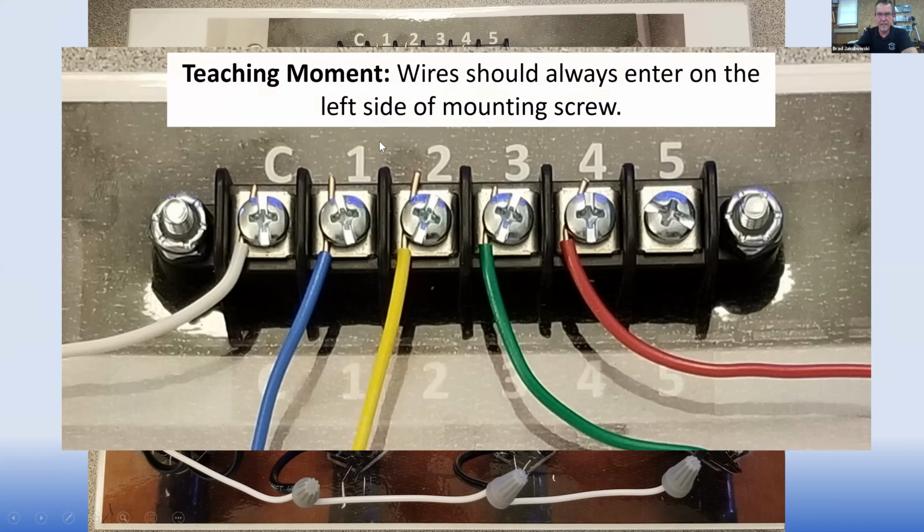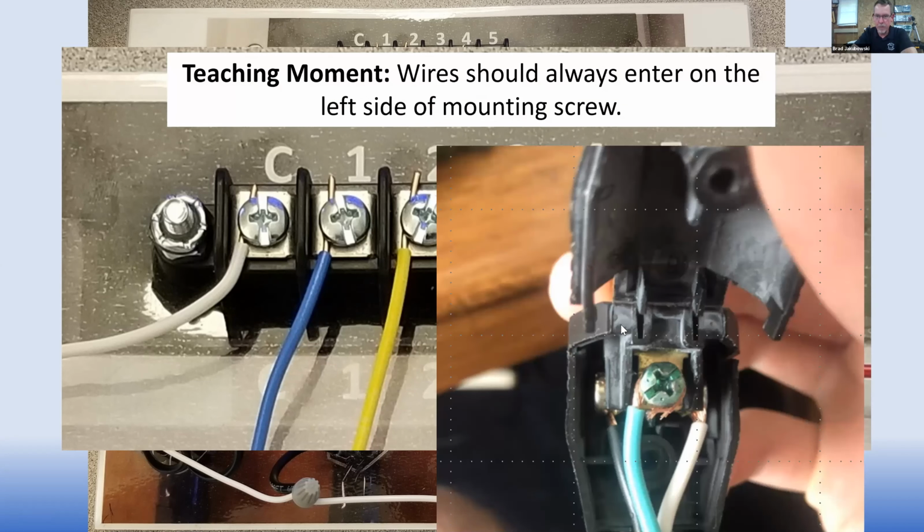So whether we're wiring controllers like this, or rewiring a plug, or building that part, because some of the controllers that we receive don't necessarily have external wiring hooked up to them, you may need to hook up a plug or a connector to an extension cord or to a cord or whatever it is. It's just as important to make sure that with your black, your white, and your green wires, you wrap it around so that it's traveling clockwise. When you screw that screw in, it's going to tighten it up and make a more secure connection. Very good. Well done.